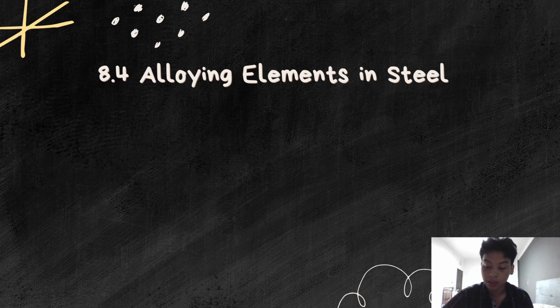Manganese is normally present in all commercial steel. Silicon is one of the principal deoxidizers used in steel making. Copper in appreciable amounts can be detrimental to hot working operations and has a moderate tendency to embrittle.